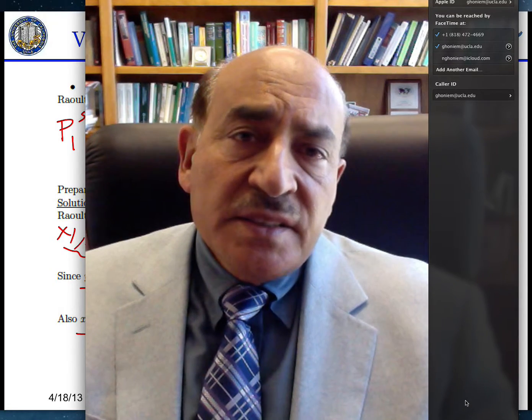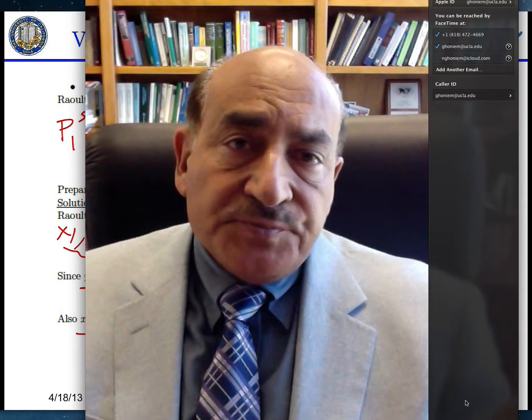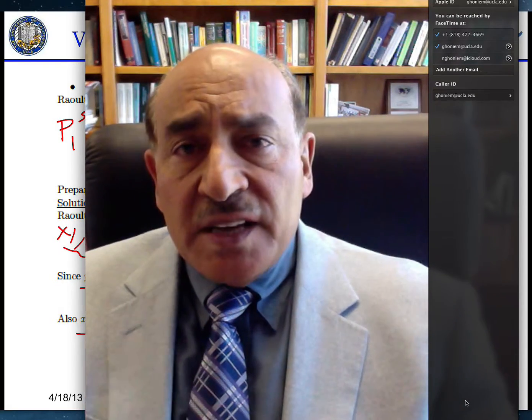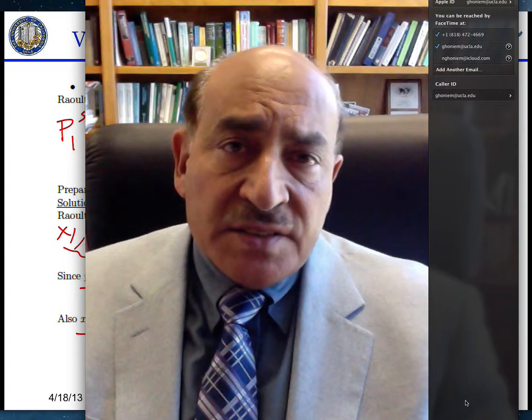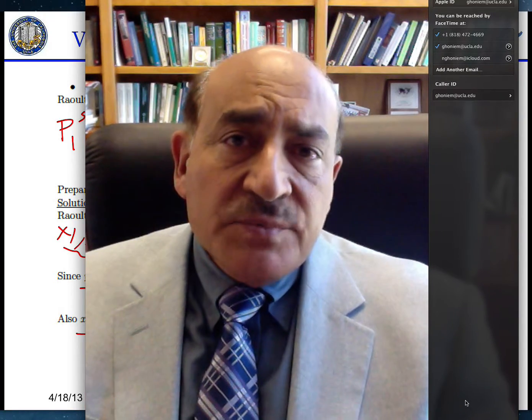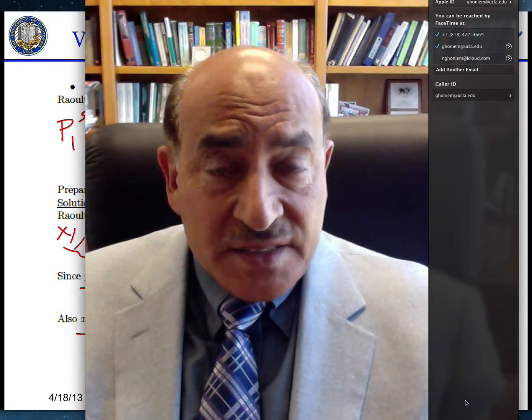And it's a linear relationship. Give me a concentration, I give you a pressure. Give me a pressure, I give you a concentration. Here x means liquid, so this is the liquidus line, the line on the liquid side, and it turned out to be a straight line. If I want to find the corresponding value of y1, the mole fraction of acetonitrile in the vapor,